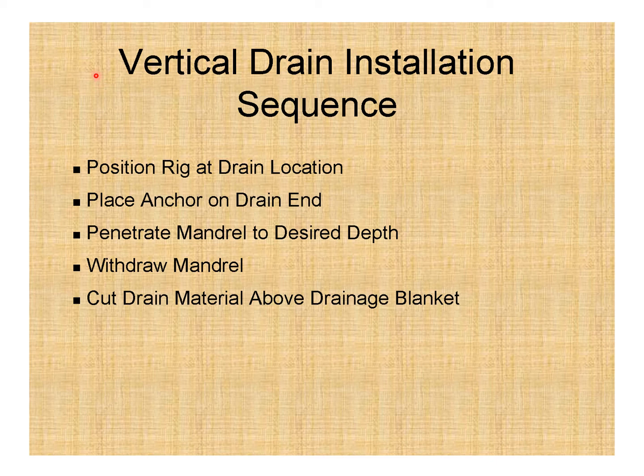Vertical drain installation sequence. Position rig at drain location. Place anchor on drain end. Penetrate mandrel to desired depth. Withdraw mandrel. Cut drain above drainage blanket.